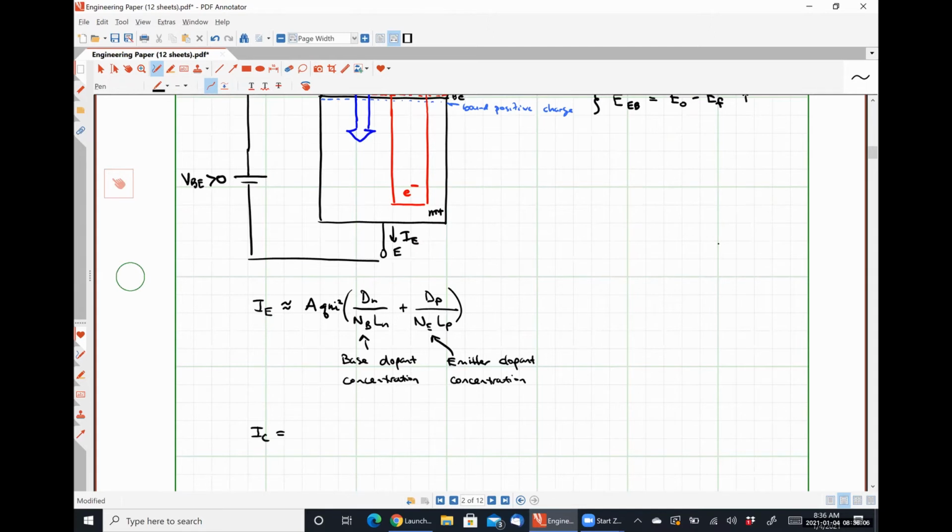but there's a couple of key things here, is going to be given by, oh, sorry, and I forgot to do this part right here. This should have been EXP. Let's see, I'm just going to call it VF over VT minus 1. Sorry, this was the coefficient which represented the reverse bias saturation current, and then it's multiplied by that same exponential bit, just like it was in the forward bias junctions earlier. My apologies for forgetting that bit. All right, so IC is going to be, and there's a derivation in the textbook that's lengthy and very, very similar to exactly what we did for PN junction, so I'm not going to bother with it.